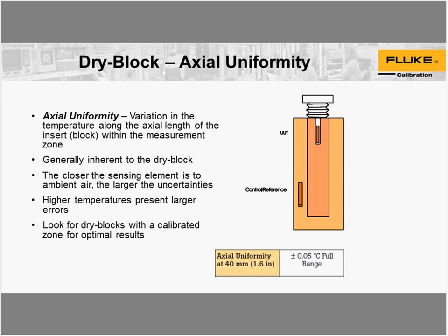But also, the heater design itself plays into this. So again, in this particular example, we're showing a worst case of a very short sensor where we have very poor immersion, and then we've got the control sensor down there at the bottom.